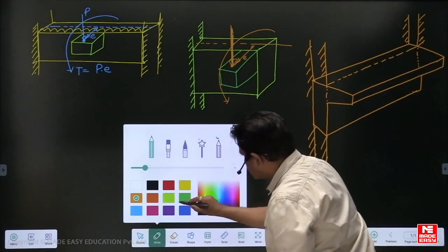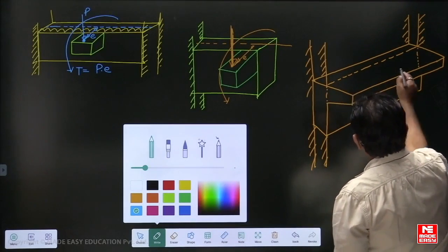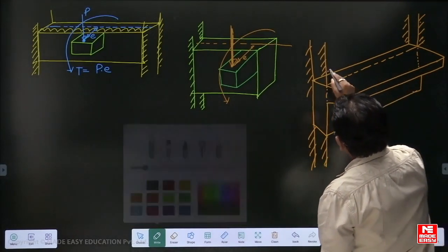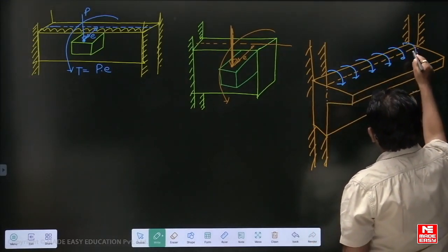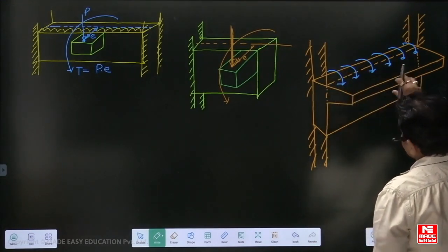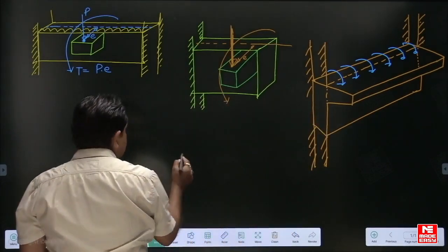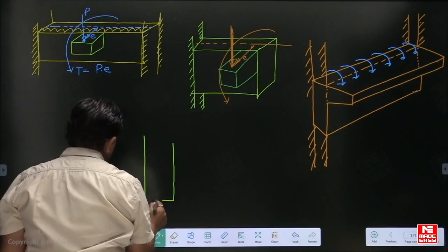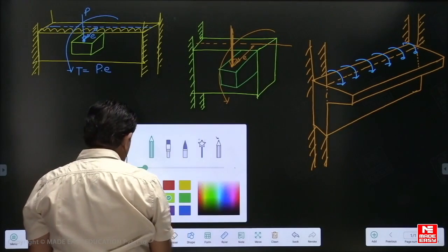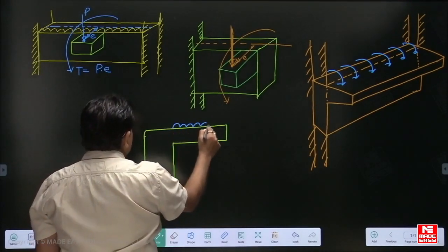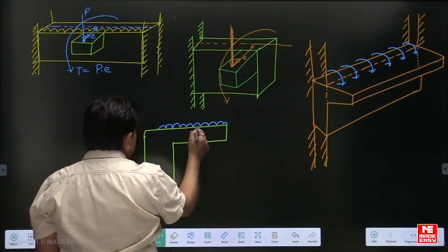So this cantilever portion of the slab will provide, whatever load is acting on this beam, torsion at each and every point of this beam. At each point you will get a torsional moment, because this beam is subjected to a cantilever slab at this location, and whatever is the load on this cantilever slab, the total load on every 1 meter length will provide a torsional moment.